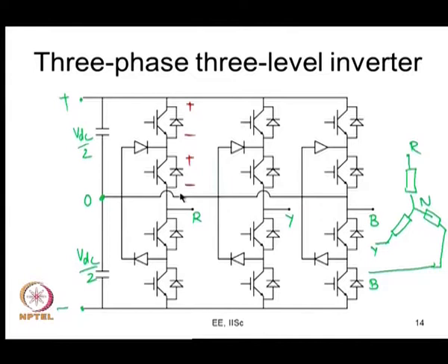That is, when you have motor drives, now let us say this 3 phase load, I have just shown it like a passive load, it could really be an induction motor connected like this, R, Y and B. So, here you would normally have motors with some voltage rating. In India the voltage ratings of motors are typically like 400, 415 or 440 volts, 50 hertz. Maybe in some other places you will have 110 volts 60 hertz or 208 volts 60 hertz, depending on the standards in different places. So, the voltage rating is typically hundreds of volts.